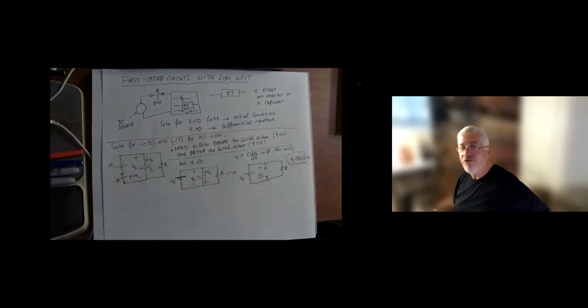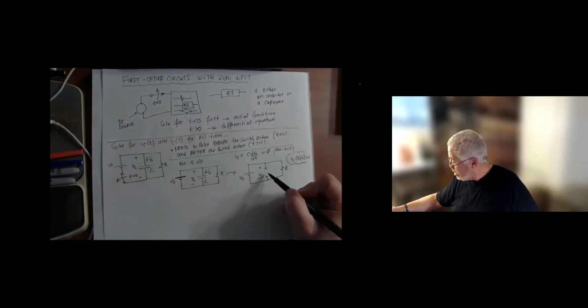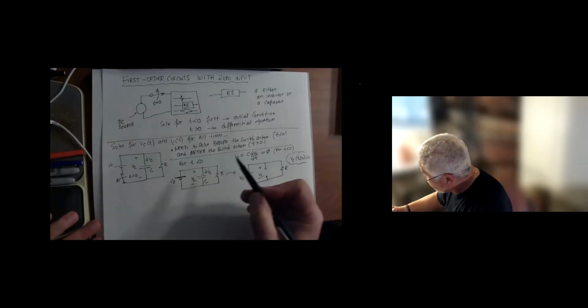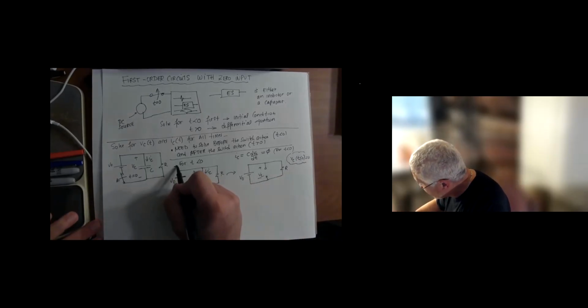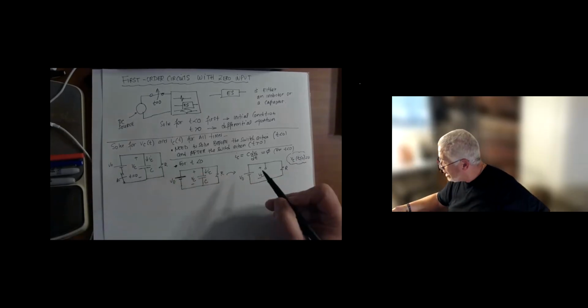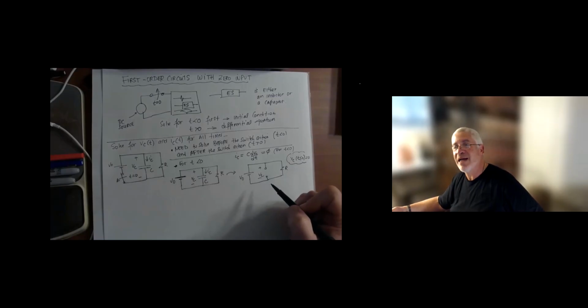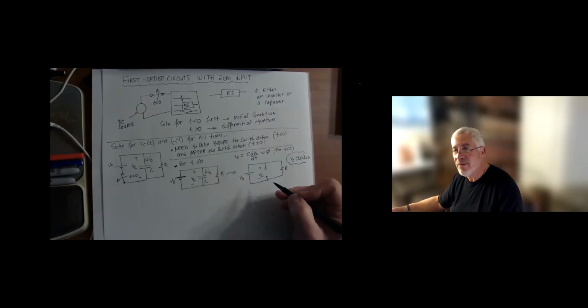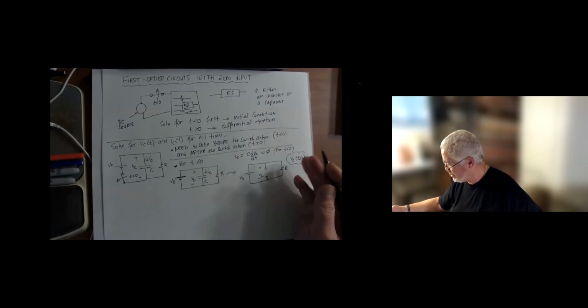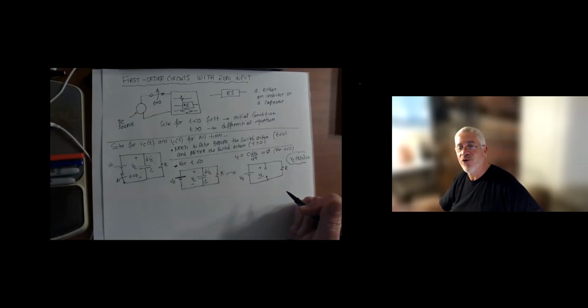So for this particular case, it's fairly simple because that's the circuit we solve. For the first time period, in this case t less than 0, you typically have a circuit that doesn't have a capacitor, because we're looking at circuits that have constant sources with switches that are switching them either on or off. So that's the circuit for essentially t less than 0.